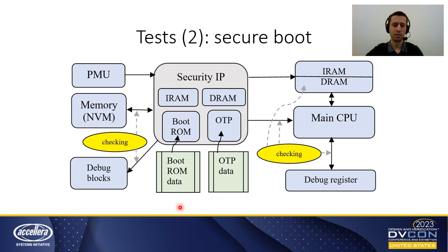However, there is another very important aspect of secure boot. Secure boot actually locks all the debug interfaces and blocks in the SoC. So at the end of this test, we need to try to access these interfaces and blocks and make sure to check that access is denied.